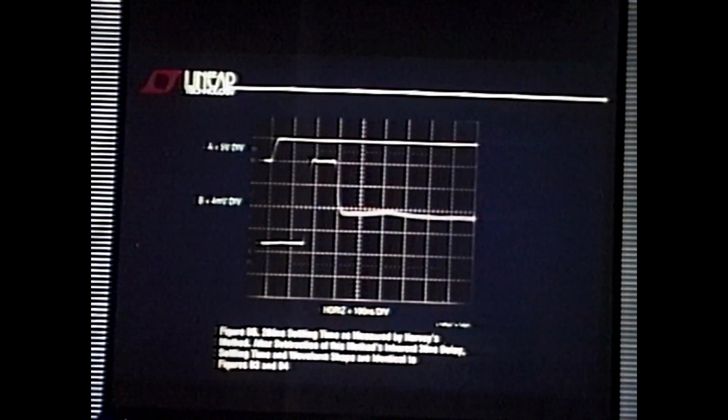Finally, there was a guy back in the 70s, actually the 80s, by the name of Barry Harvey, who published a method which was similar, the same kind of thing. He clips the measurement in time. What I consider to be a much more complex method, but I went ahead and built it anyway and measured it with that method and got about 300 nanoseconds. But if you study Barry's paper very carefully, the way the thing works, you get to subtract 30 nanoseconds. So you go, yeah, that's pretty good. That's about 270. Fine, we can build this product and ship it and spec it at 280 nanoseconds.